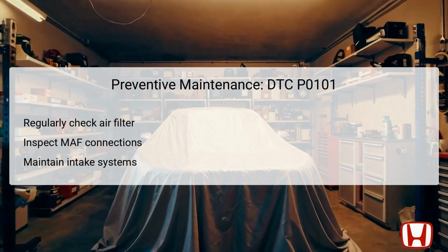Maintaining the entirety of the intake system, including ensuring that there are no blockages in the intake ducts or housing, can greatly enhance the longevity of the MAF sensor's performance. By incorporating these preventive measures into routine vehicle maintenance, owners can drastically reduce the risk of similar issues arising in the future, ensuring smoother engine operation and improved fuel efficiency.